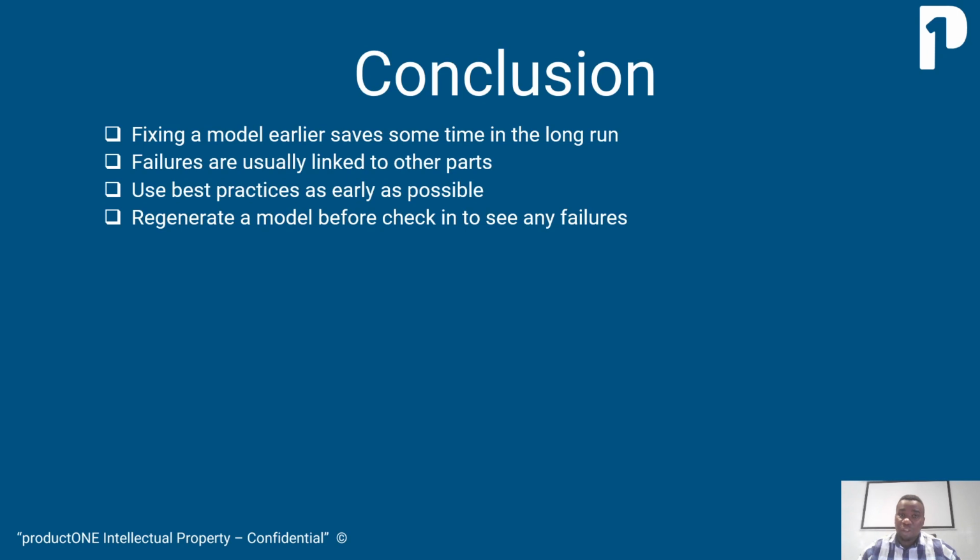Regenerate a model before you check in to see if there are any failures. This is important, because sometimes you can check in a model, but if you have not regenerated it after you've checked in, it can create some problems, and those problems can affect other systems as well, such as your ERPs and so on.